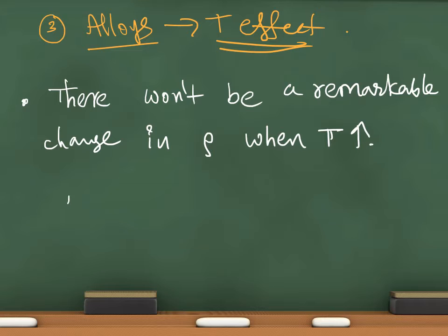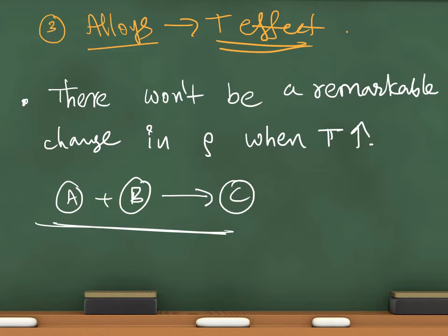Why? There is a hybrid combination in these alloys. A will have some resistive property and B will have some more resistive property. But in this case, the resistivity is increased due to the adding of the foreign body in most of the cases. What will happen if we increase the temperature?